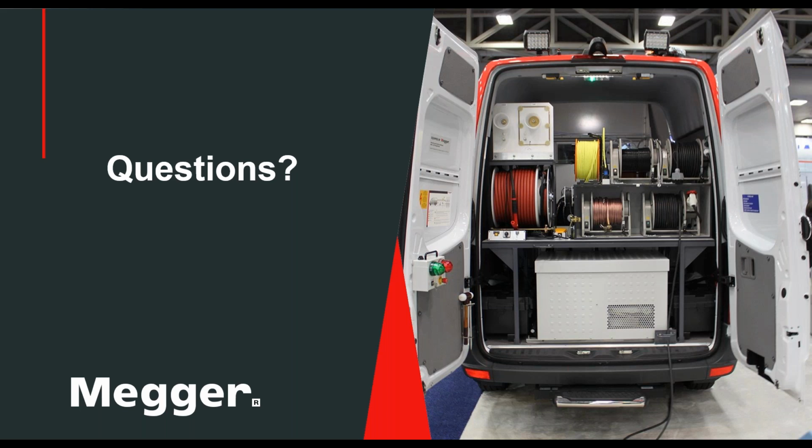Maybe Henning, just one brief add-on. The ST25 will go to 30 kV high pot, right? So in general, it's a good thing to always check the breakdown voltage, even when you work on a 230 kV cable, because most of the time breakdown voltages, especially on high voltage cables, are fairly low because of the amount of fault current present. So for the most part, you can find faults with a medium voltage fault locating system on high voltage transmission cables.